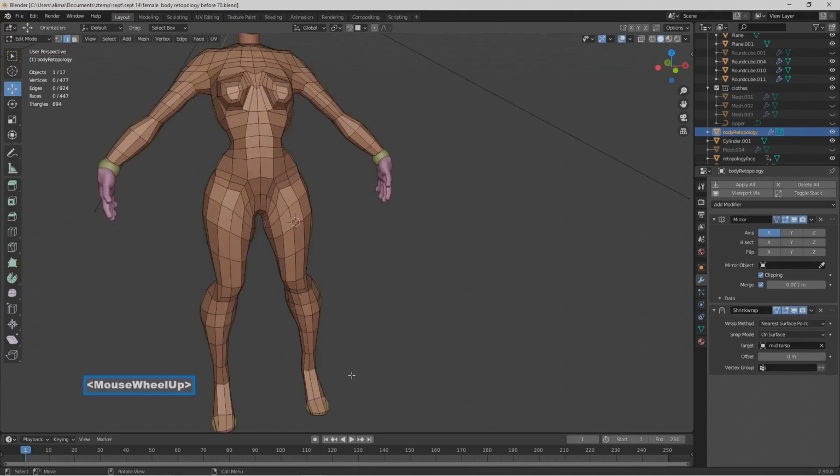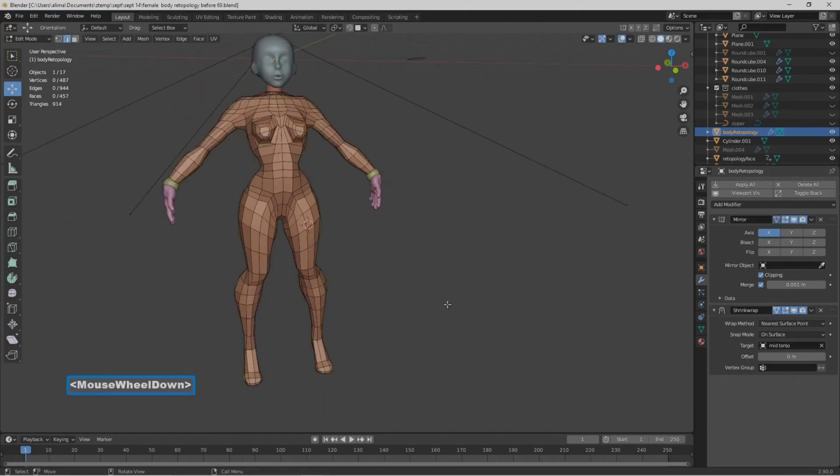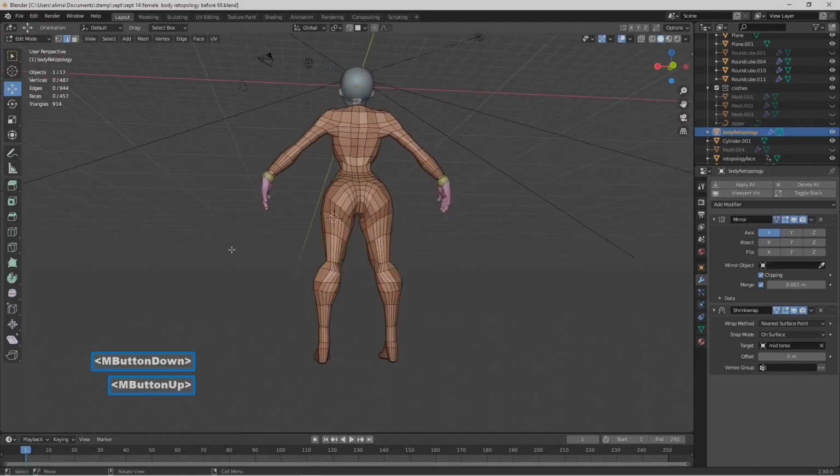Okay, looking here, we can hold control, press R, left click once, left click a second time to put a loop cut in there to have our retopology mesh conform more to the shape of our sculpted mesh. Okay, I'm going to roll back, hold the middle mouse button. When we look here, we can see this geometry looks kind of strange.